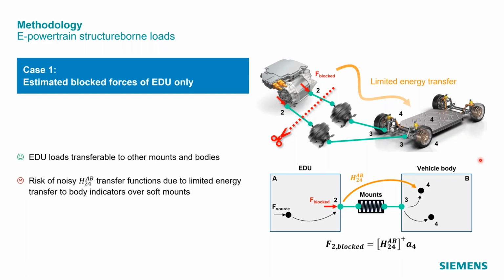In summary, for this method, there are some advantages and disadvantages that we can identify. On the advantage side, what I do like about this strategy is that the interface is nicely separating our powertrain from the rest of the assembly. So these blocked forces at this interface points are very valuable